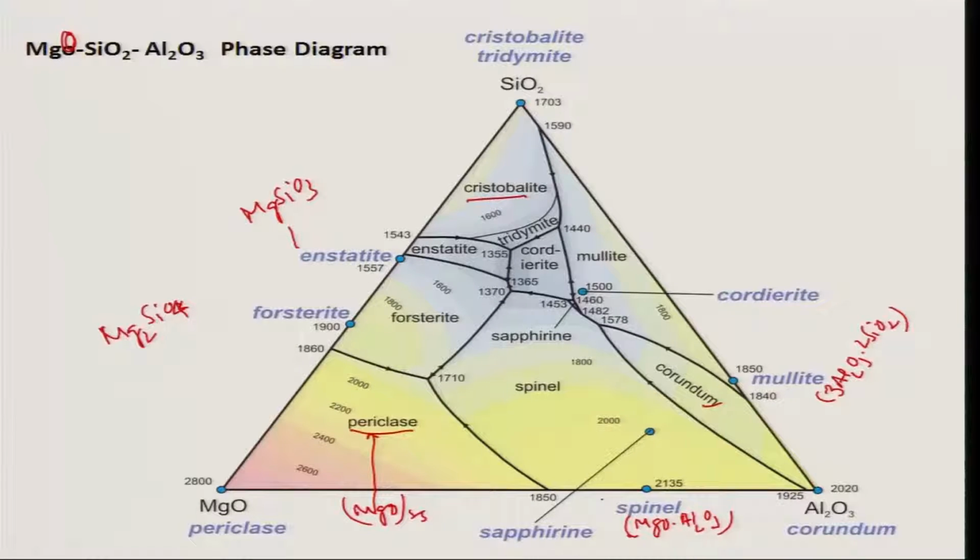Okay. So, you can see here it is stable for a large Al2O3 composition range, also it is stable for a large MgO SiO2 composition range. So, SiO2 addition actually increases the stability of the spinel. Then you have forsterite. Forsterite basically is a binary MgO SiO2 compound, but addition of aluminum oxide Al2O3 actually stabilizes forsterite. So, you can see the forsterite is getting stabilized in this part of the region. Enstatite is basically stable for a small composition region, and there are a few important ternary compounds. Let me just discuss.